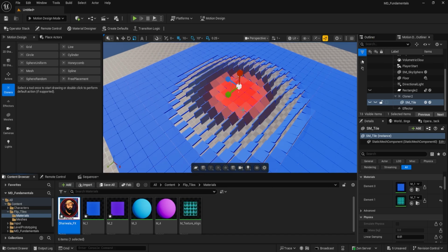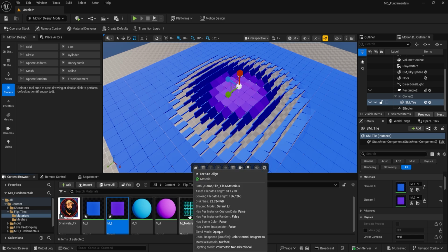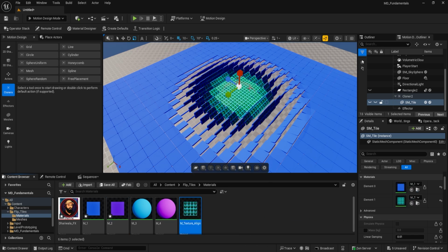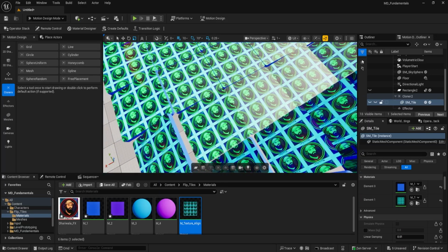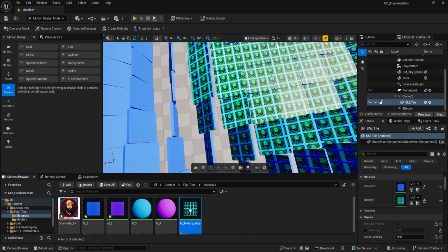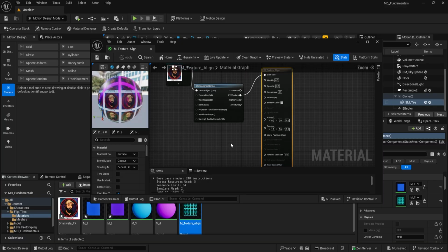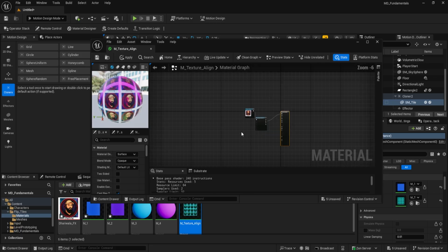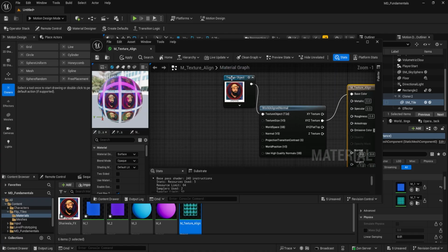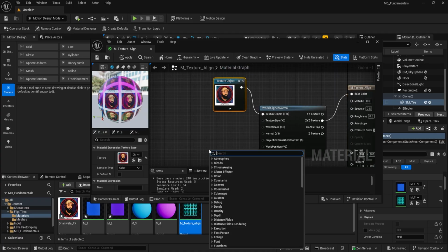So you can see, just save this one, and here you can see if this material does not work, how you can change is just drag this one and after that change. So you can see our image is applied now. So here just double click, and from here you can also change its roughness to 0.8.